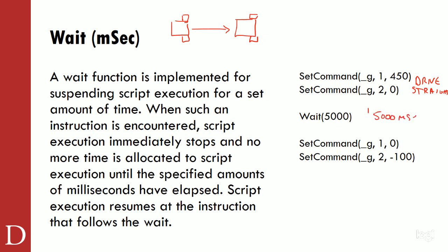So he's just going to continue driving because there's no other commands coming to him because we are paused in the execution of the code. We're not going to go on beyond that. But now when we get past that 5-second window of him driving straight, now we're going to, instead of waiting, because we executed this, and now we're here, pick up the code again after 5 seconds. At that point, you can see what we did is our throttle went to 0 and we started turning to the right. So what he's going to do now is he's going to turn in place.